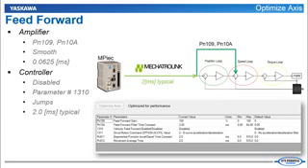Feed forward takes the speed of the position command as an input to the speed loop and results in reduced position error. The amplifier internal feed forward gain and filter result in a smooth response because they operate at the internal update rate of the amplifier. The controller feed forward operates at the mechatronic cycle, typically around 2 milliseconds.